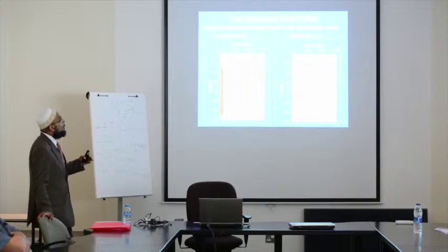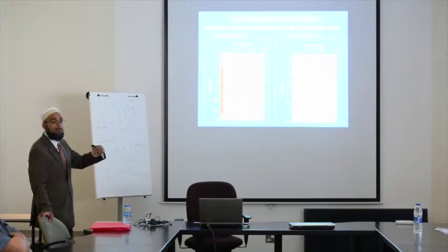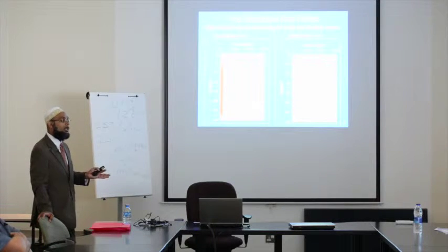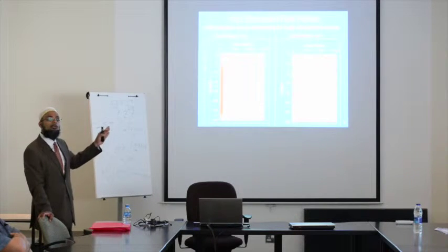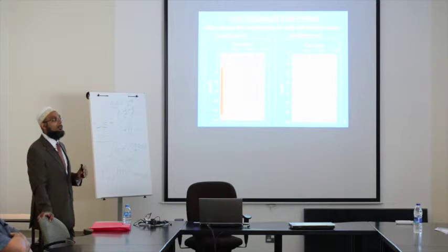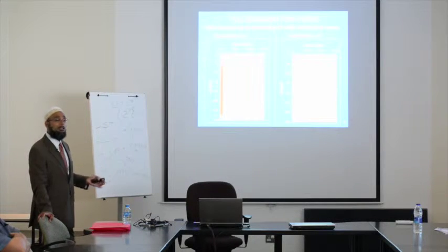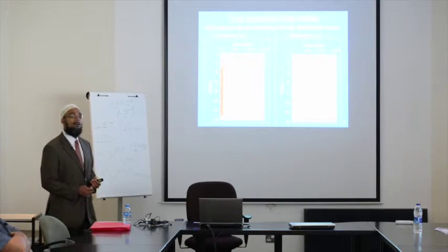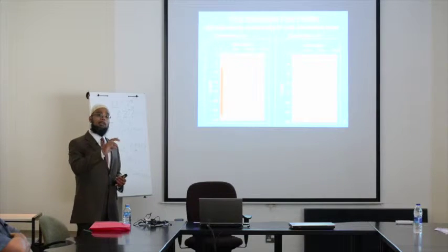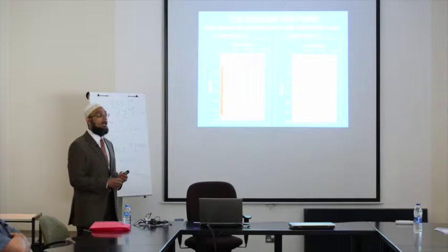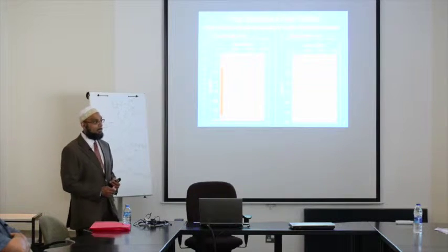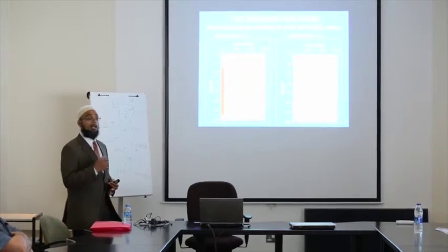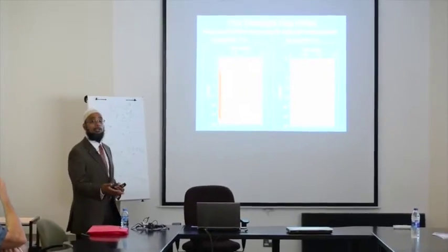Okay? And over time, the differences get larger and larger, because when you come back and try to re-stimulate this well, since the first treatment was not correct, you not only have to fight the big permeability contrast, but now you have zone 1, which is high perm and stimulated, it has a negative skin, and if you come after maybe a few years, it is also low pressure.